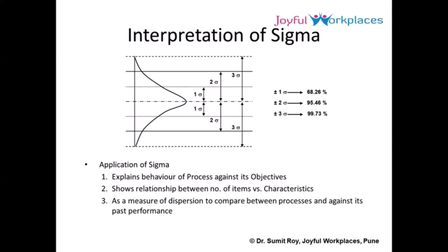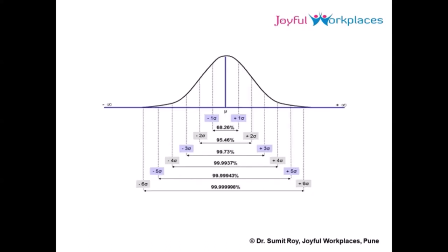Now please notice that when you are calculating the upper control limit and the lower control limit, actually, you do not require any spec limit. Please understand that part, first of all. Spec limits are defined by whom? Designers. And who is defining upper control limit and lower control limit? Your process.